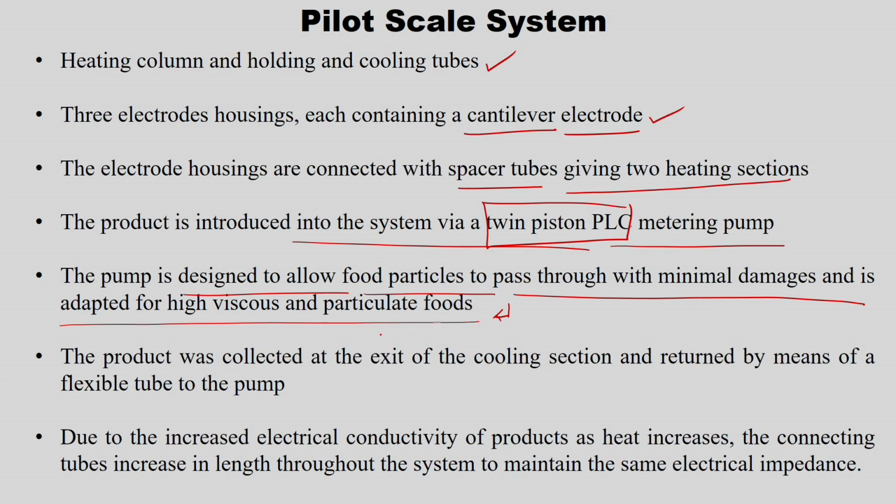So, we need to design the pump accordingly, which should allow fluid food particles to pass through with minimal damage, and the product was collected at the exit of the cooling section and returned by means of a flexible tube to the pump. And due to increased electrical conductivity of the products as heat increases, the connecting tube increases in length throughout the system to maintain the same electrical impedance.